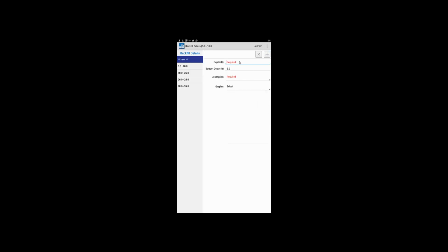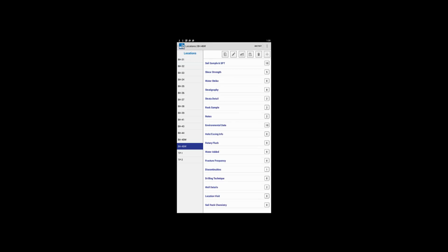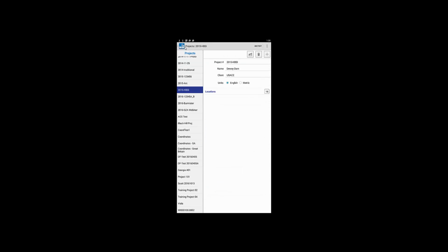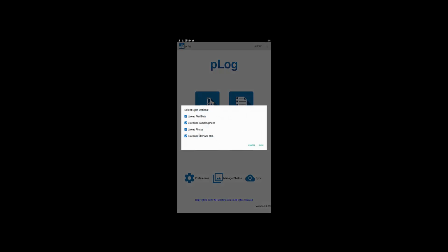And then finally we'll say from 0 to 5, maybe we're going to use, I don't know, what do we want to use this time? Maybe cement? Sure, let's go with cement. And we'll indicate that the graphic is going to be concrete. Okay, so we've now backfilled our well, and we will now upload this data to pLog Cloud. So I'm just going to upload the field data.